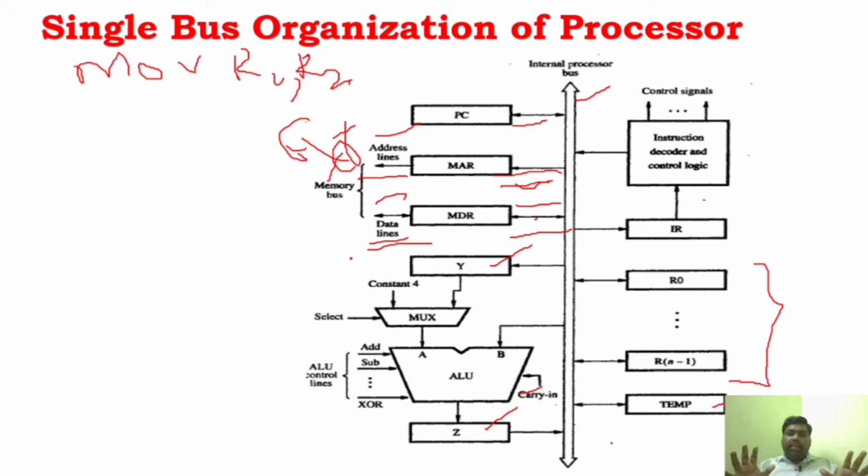So far clear? And you have to explain about the ALU. We have already seen the design of the 2-bit ALU, 4-bit ALU, all those things. If you take the ALU, you have control lines like add lines, sub lines, XOR lines, depending upon the operation. If you need an add operation, the add line will be enabled, and similarly, if the sub line is enabled, then it will perform subtraction. And very importantly, you have to understand the ALU has only two inputs, A and B.